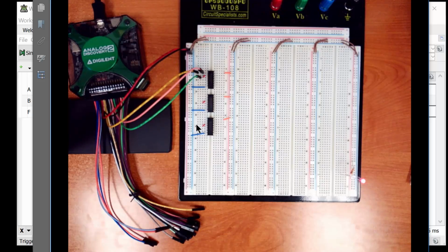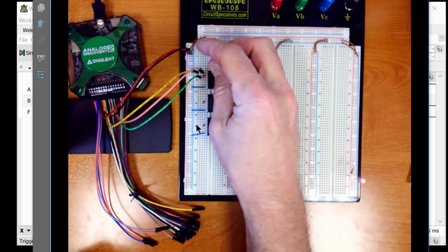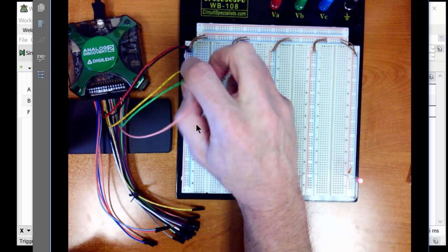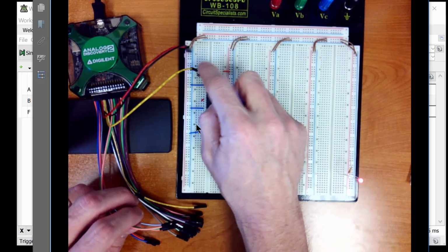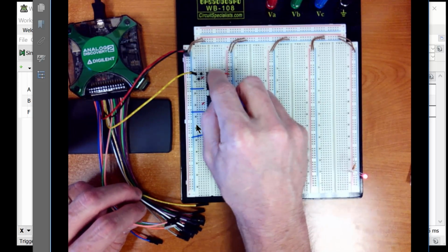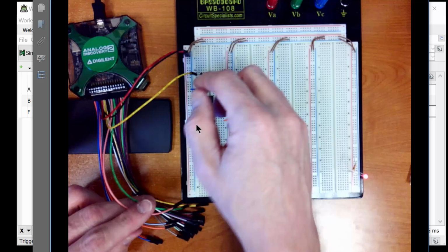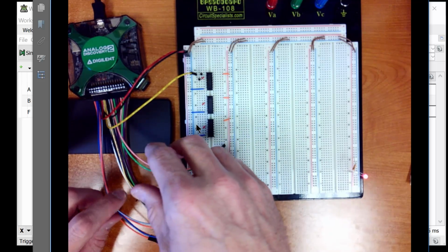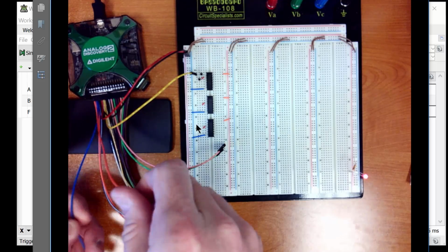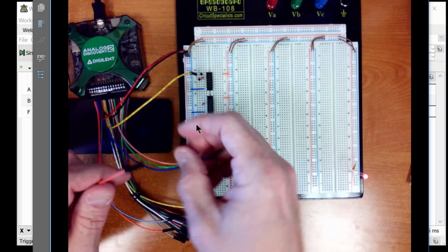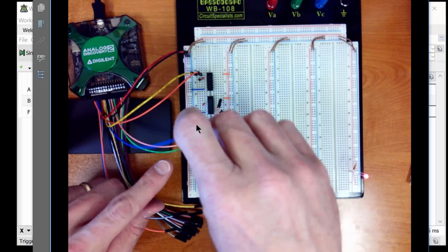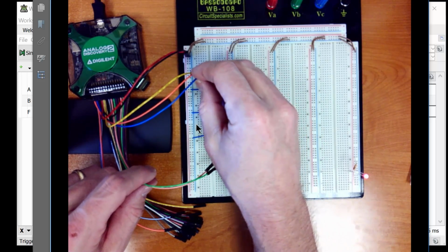So if you go back to your breadboard, what you're going to want to do is disconnect the logic analyzer channels, and I'm going to take those over here. I just leave my jumper wires or pins in the same position because we're going to measure the input and the output using the 2 channels of the oscilloscope. So now on the oscilloscope, grab 1 plus and 2 plus, which are the oscilloscope channels, and let's put channel 1 on the input to the inverter. We'll put channel 2 on the output of the inverter.